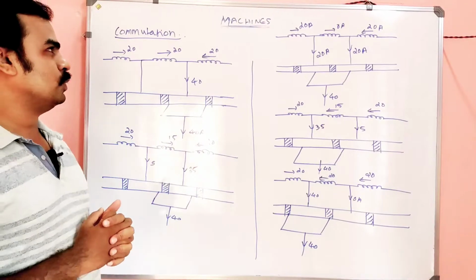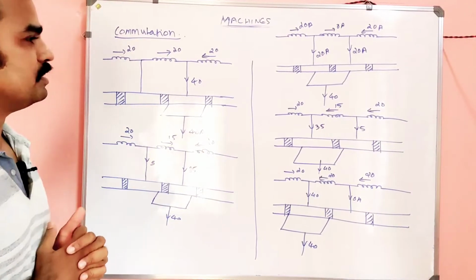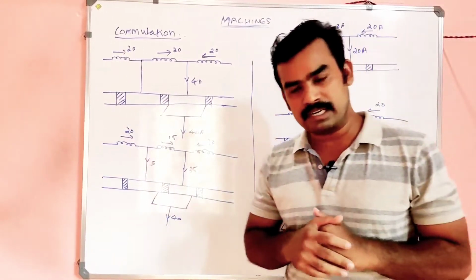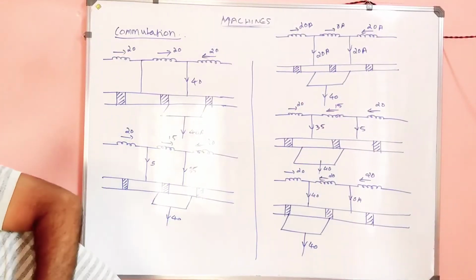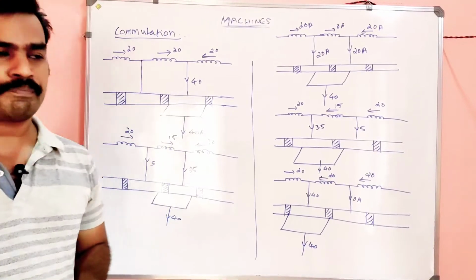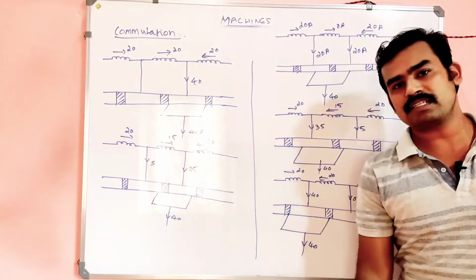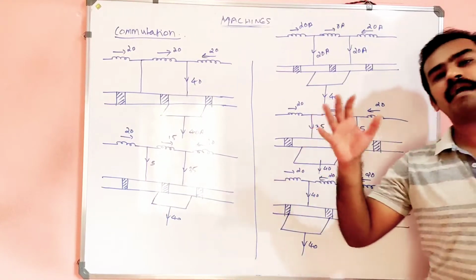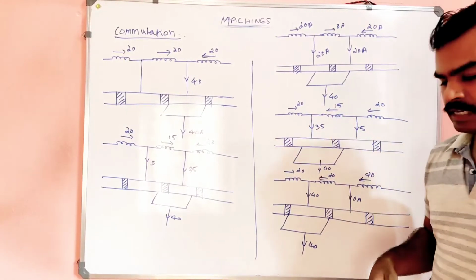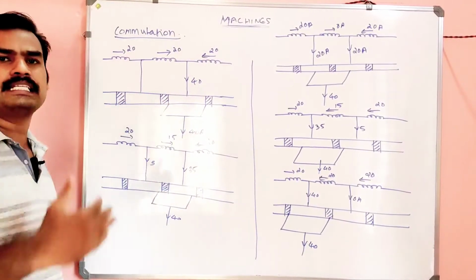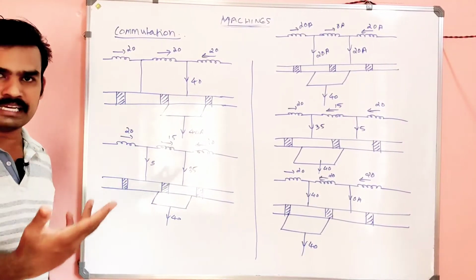So today, in the last class we discussed the concept of armature reaction, right? There are a lot of problems in armature reaction, especially that it will distort the original field flux as well as demagnetize the original field flux. So definitely this will lead to a dip in voltage, a decrease in the induced EMF, right?